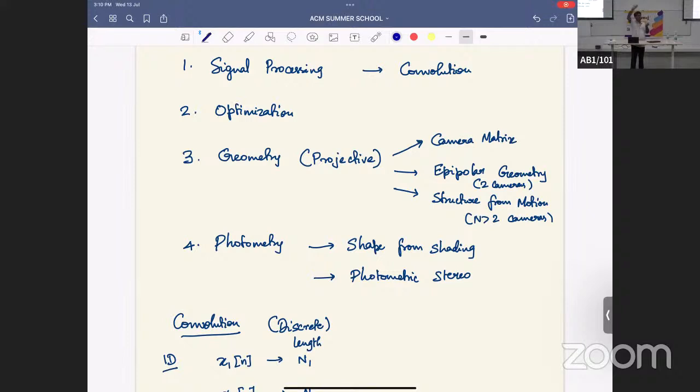So it has removed the high frequency details, which are the details you want. For example, the number plate may not be visible. The number plate has sharp edges, which are a high frequency component. But the physical system had a convolution kernel enforced on the camera, doing a low pass filtering operation. That's why you got the blur.